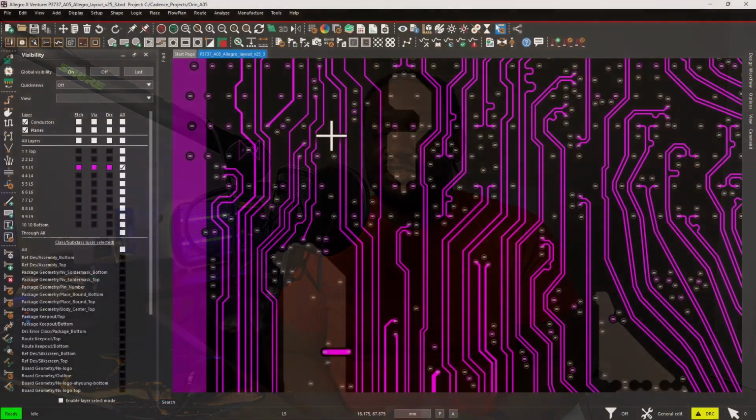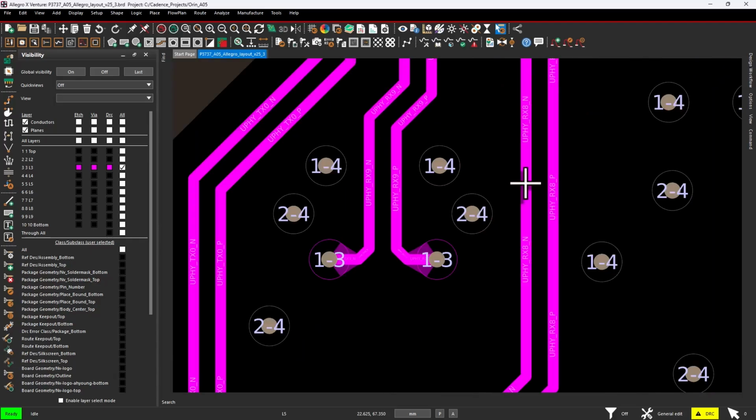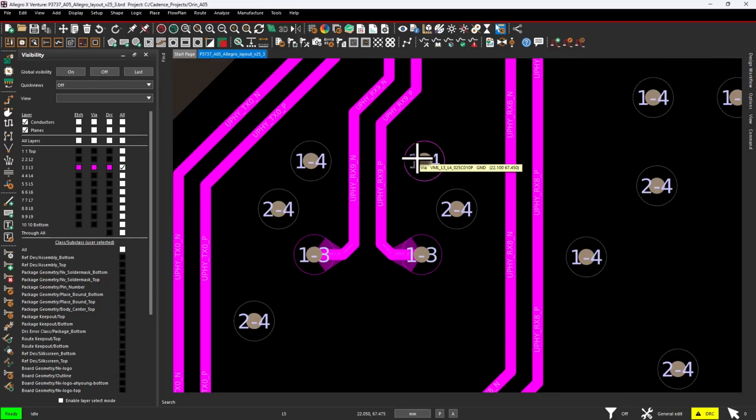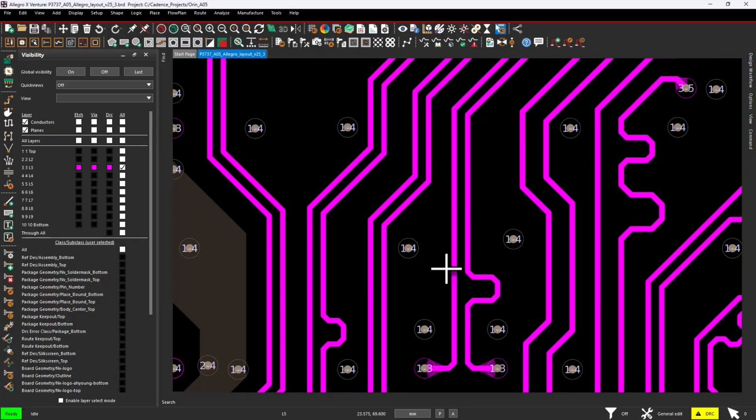So what's the fix? The fix is to place an adjacent ground via right next to any via transition you make on the PCB. NVIDIA's Jetson AGX Orin carrier PCB does this perfectly. Every signal via transition has a ground via right next to it, which keeps the EM wave from spreading to other conductive structures. At gigahertz speeds, not placing a return path via will cause problems.